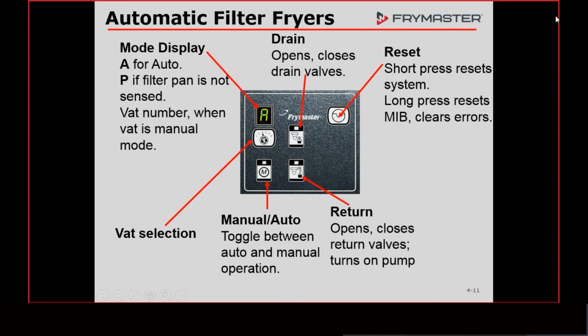Same way with boiling out. A boil out is an hour-long process. If you're just cleaning the pots, you can put water in there and then drain it using this board. Just always remember, you override the safeties using this. And one rule on using this board is if you're getting ready to push one of these buttons, make sure you know what's about to happen and make sure that you're prepared for it.